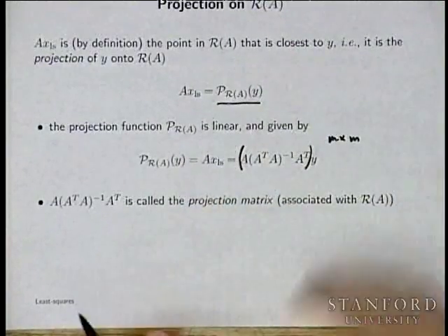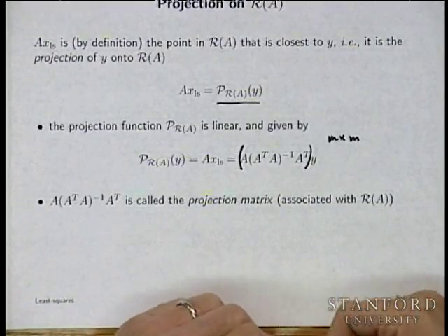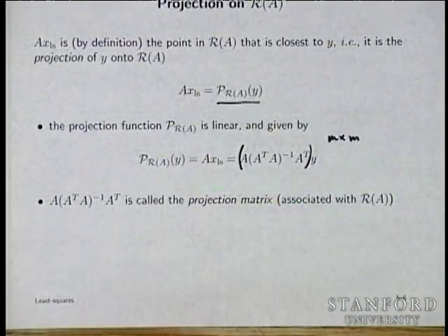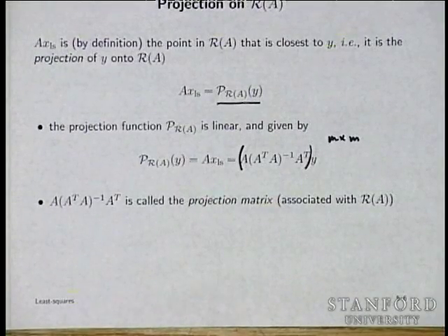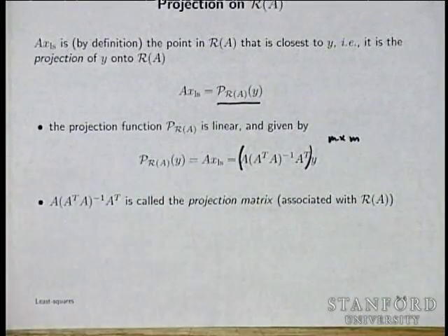By the way, this already has lots of uses. You can actually imagine something like this. You receive a signal with noise, a vector signal, say in a multiple antenna communication system. But you happen to know that the signal should lie in a certain subspace, the range of A. You can simply then project onto the range of A, and what you've got now is the closest signal to the one you received, which is consistent, that's in this known range. Okay, and this is used.